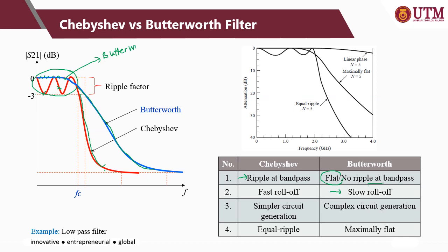If you have a higher filter order number, then you'll have steeper lines. For example, n equal to 1 versus n equal to 5. If you have n equal to 1, the line will look something like this. But if you have n equal to 5, then you will have a steeper roll off.